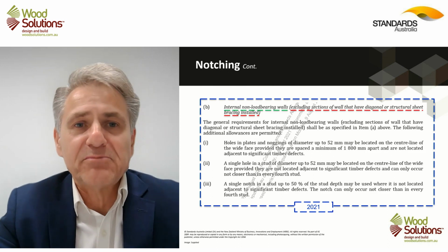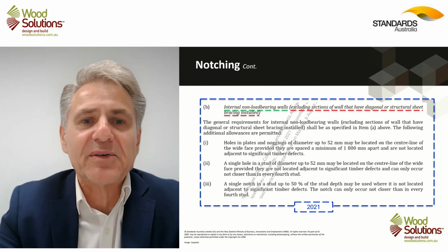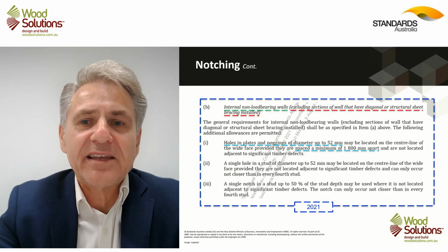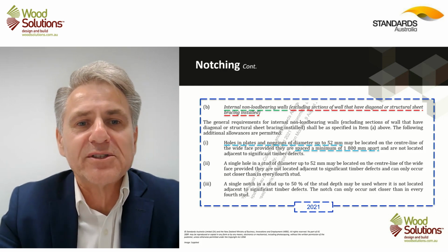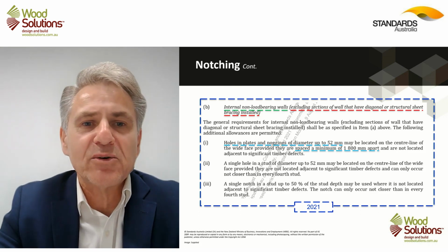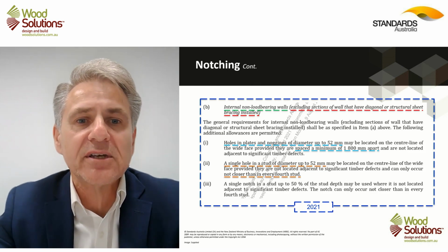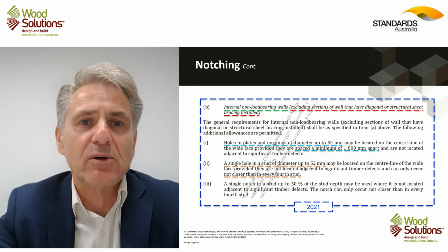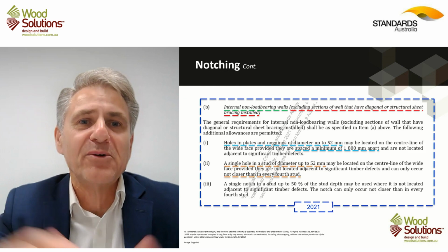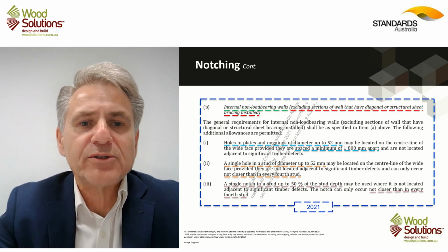So we'll have plumbers and fitters trying to put pipework through elements. They're encouraged, obviously, to put them through non-load bearing walls. And there are specifics provided about hole sizes for top and bottom plates, as well as noggings within our wall frames. Also, hole requirements within the studs and spacing of those holes. So you don't want a continuous row of holes through your wall, so that you provide no lateral stability to that wall. And also notching requirements.